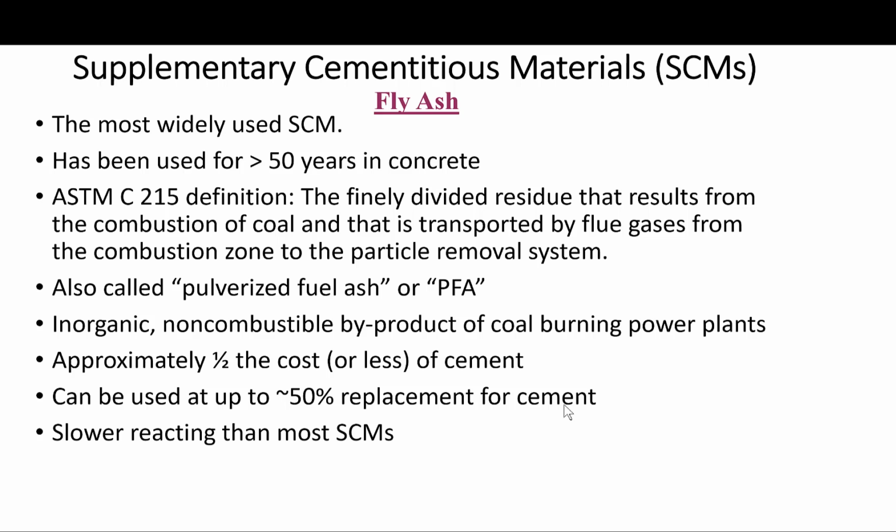As power companies also turn to scrubber systems to remove sulfur dioxide from stack gases, many fly ashes become mixed with the scrubber products and contain free lime and calcium sulfates or sulfites. Okay, and that also renders them not suitable. So these materials cannot be used in concrete, for obvious reasons. So it is advisable to purchase fly ash from a reputable supplier to ensure predictable and reliable performance.